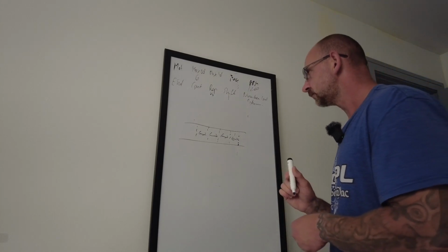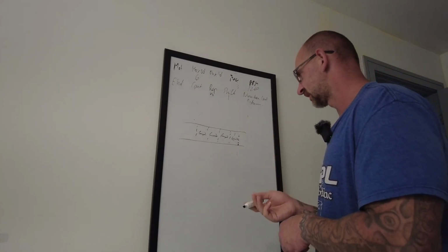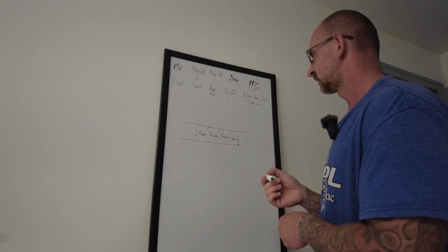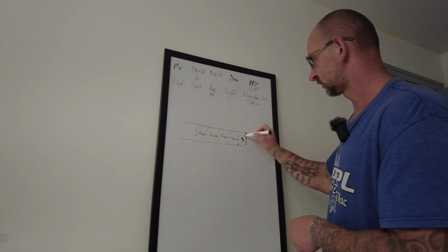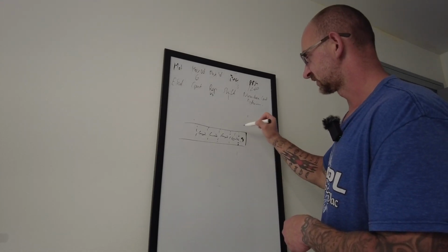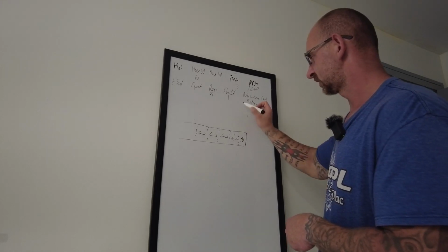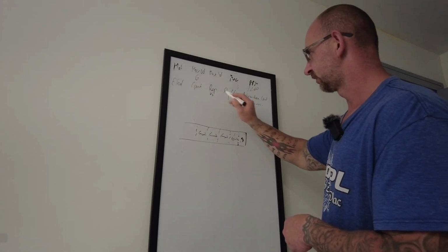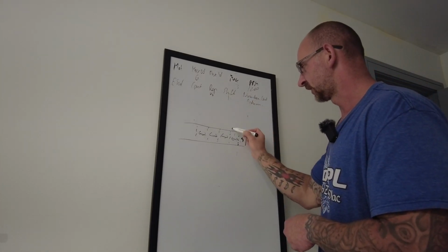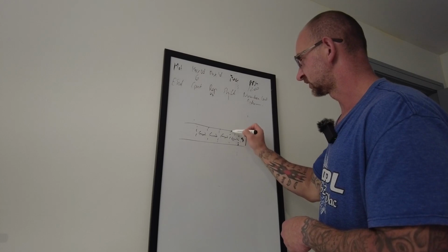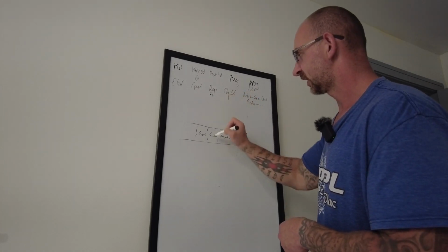You write a unit that's going to be drilling, for example, using live tooling, and the start is going to be 0.5 inches from the face. So your Z is 0.5 inches, your starting point, and then you finish. Then you tell it to repeat 5 times and shift 1 inch. It drills all these holes, comes up, shifts again 1 inch, goes up and continues.